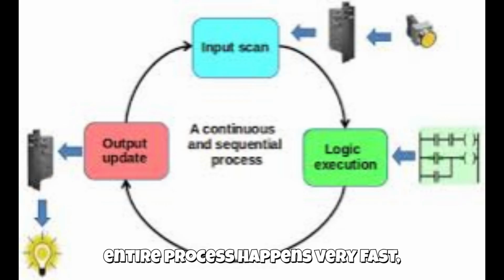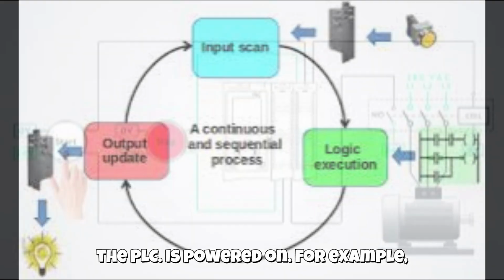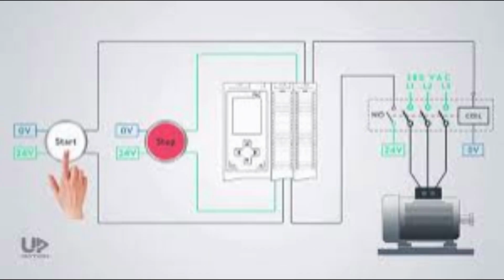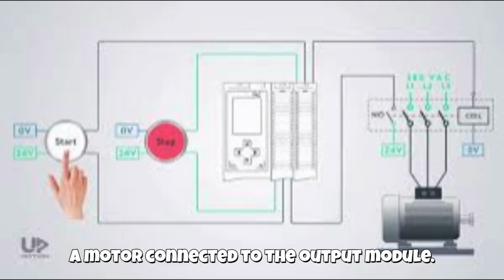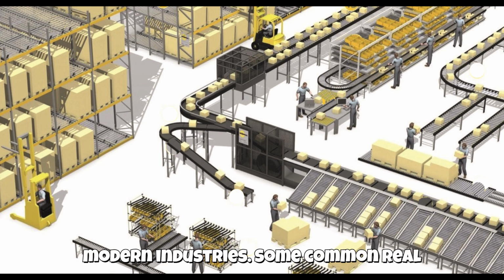This entire process happens very fast, typically within a few milliseconds, and keeps repeating continuously as long as the PLC is powered on. For example, if an operator presses a start push button, the PLC reads that input signal, processes the program logic, and turns on a motor connected to the output module. Because of this fast and reliable operation, PLC systems are widely used in modern industries.